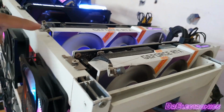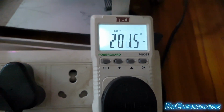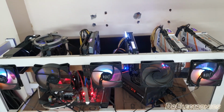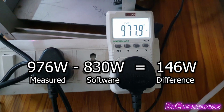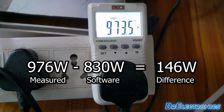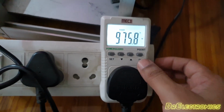And when HiveOS is done loading up, it will generate the DAG file and we'll start mining with this rig. We can see 200 watts being taken up by the system when it is initializing to mine, and when it starts mining we can observe that the system is taking around 976 watts. On the wall we are getting 976 watts, in the software we are getting 830 watts. The difference is 146 watts.